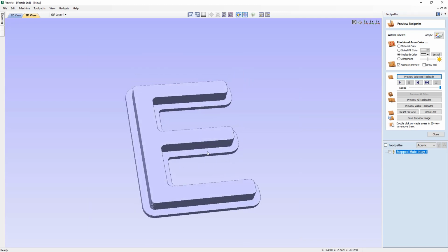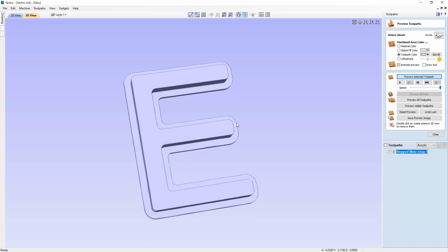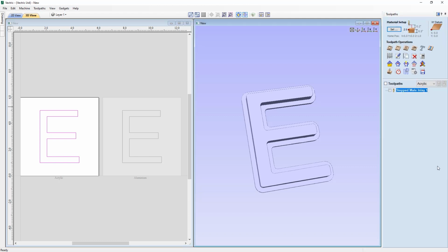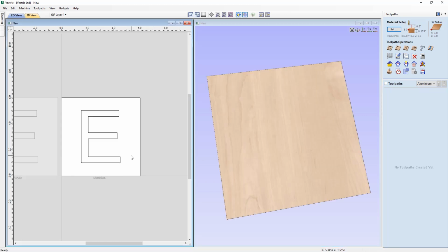So here is the width of our step, and then this is the depth, so we're left with 1/8 of an inch there, and the idea is that's going to push through into the female part where it just sits flush on the back, and so we'd only see the actual protruding letter going through the letter there, and this just enables us to kind of just fix this to the back of the female. Okay, so if we go ahead and tile our windows, and then we can simply close out of the preview toolpaths form.